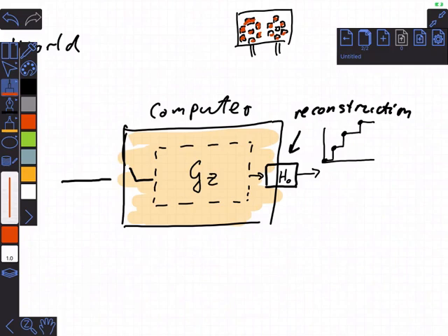And when we're using something like Python code, a zero-order hold is effectively the automatic behavior of variables. So I update a variable at a certain moment in time, and if I look again at that variable in some intervening time, it will just have the value that it had last time. So zero-order holds are easy to implement, they have very low latency, and they are the kinds of things that we will be studying in this course.